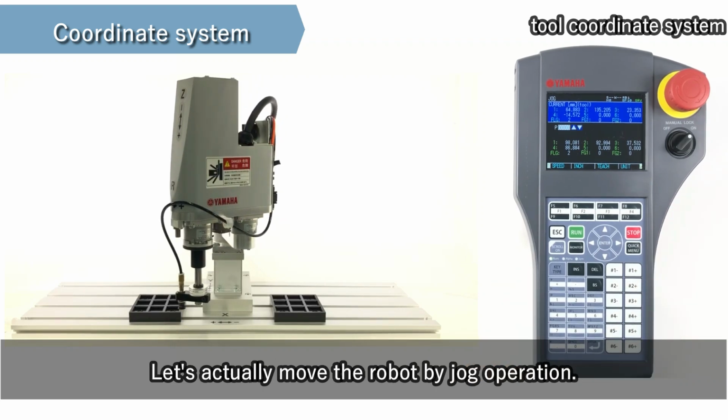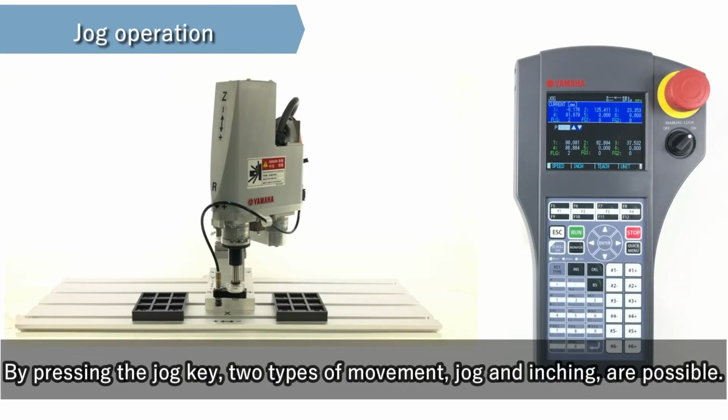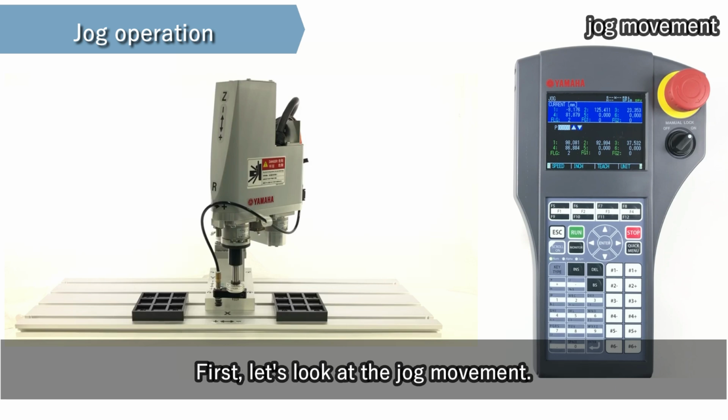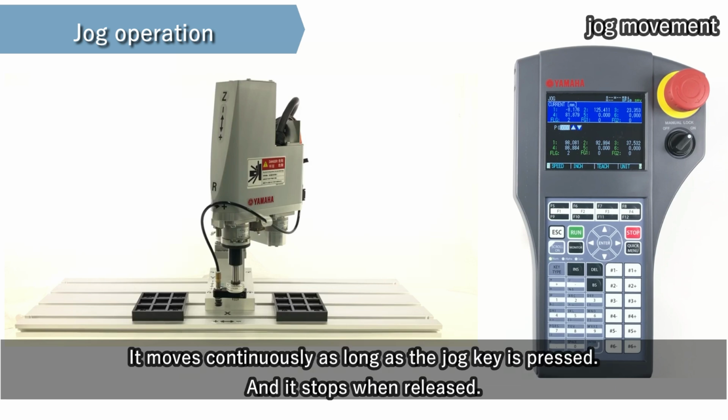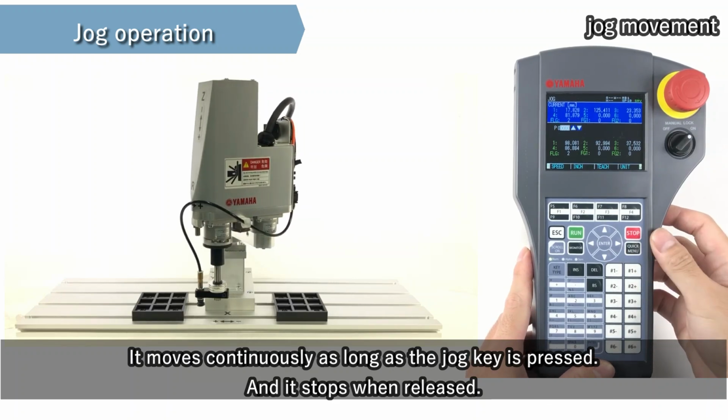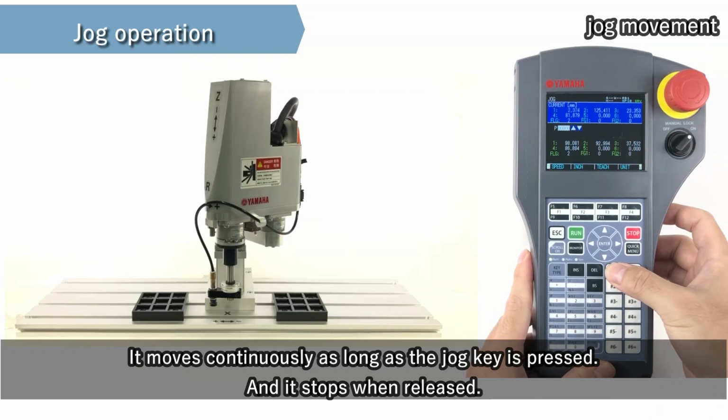Let's actually move the robot by jog operation. By pressing the jog key, two types of movement, jog and inching, are possible. You can select according to how you press the jog key. First, let's look at the jog movement. It moves continuously as long as the jog key is pressed, and it stops when released.